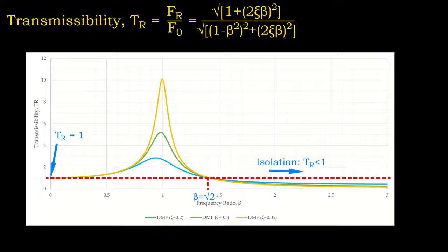The effect of frequency ratio and damping ratio on the force transmissibility is the same as those for the motion transmissibility. In any case, it is desirable to have small transmissibility, best if it is smaller than 1. Transmissibility greater than 1 means the excitation is amplified once it reaches the other end of the system, and more effort may be required to mitigate the subsequent effects.